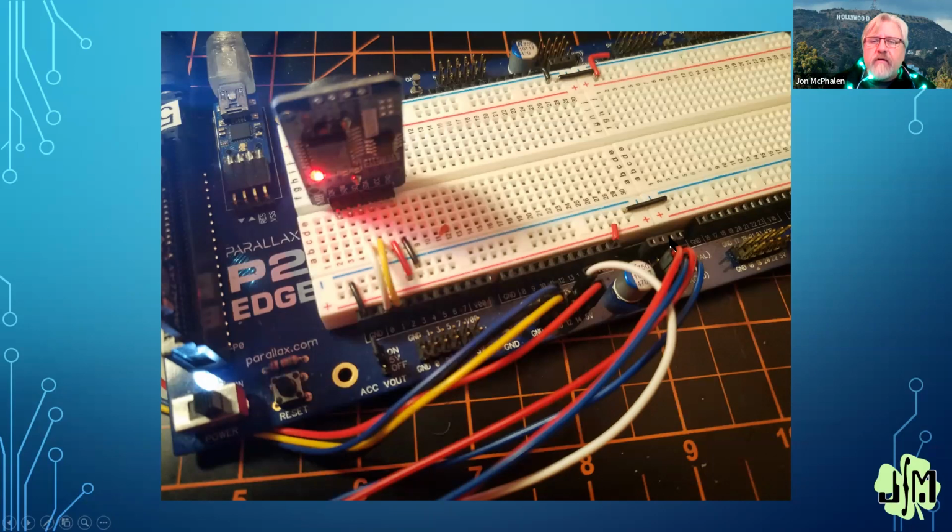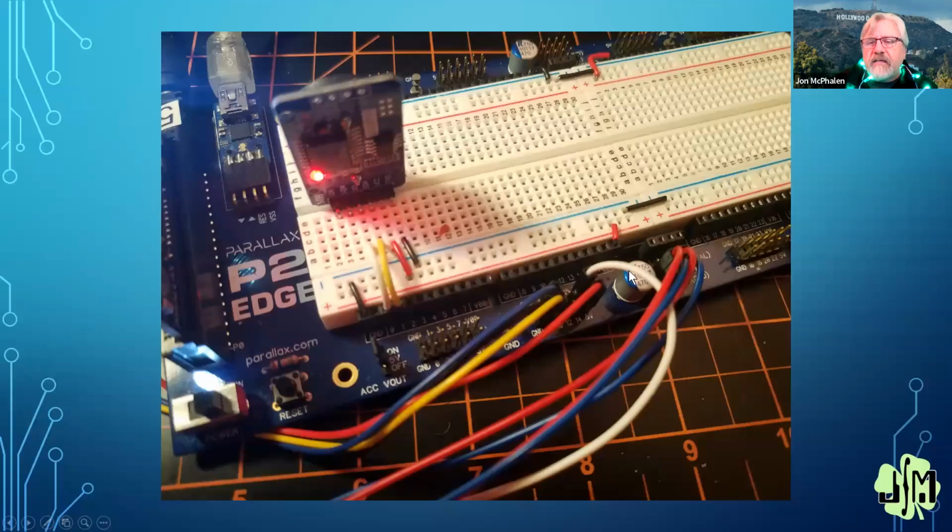And then these wires are for my displays. I don't know if this will show up, but there's a black 3-pin connector on the wires. I just extended those out with male-female jumpers, and then there were 2 loose pigtails, and I extended those with jumpers as well. So you'll notice I've got 2 reds and 2 blues here. The reds are 5 volts and the blues are ground. I put them over here on this servo port because there's this buffer capacitor right there.